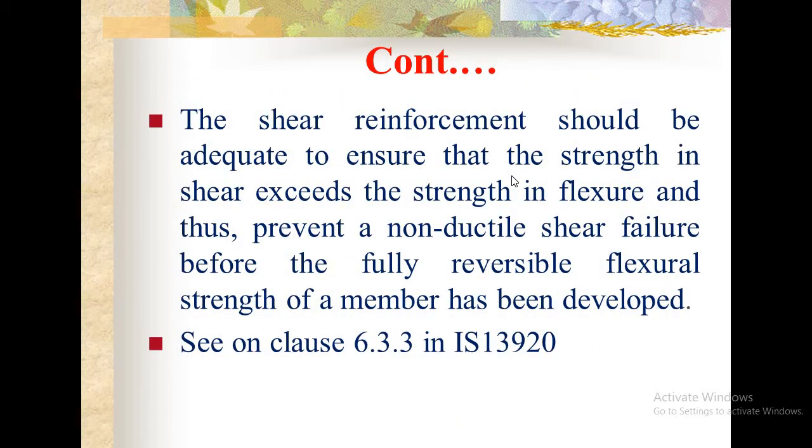The shear reinforcement should be adequate to ensure that the strength in shear exceeds the strength in flexure, and thus prevent a non-ductile shear failure before the fully reversible flexural strength of the member has been developed.